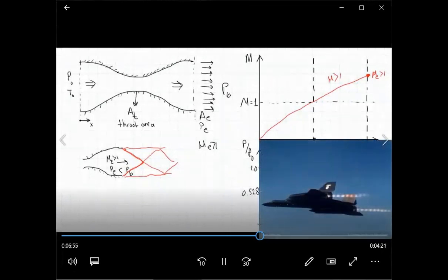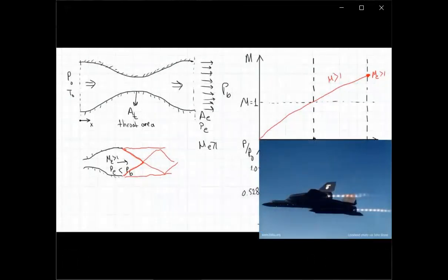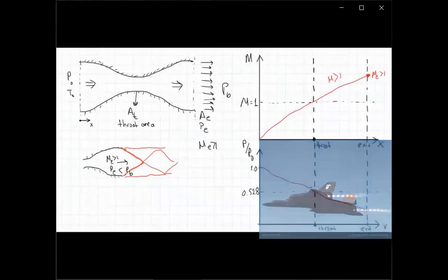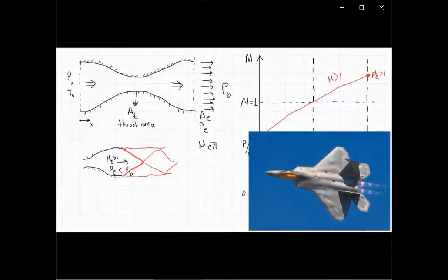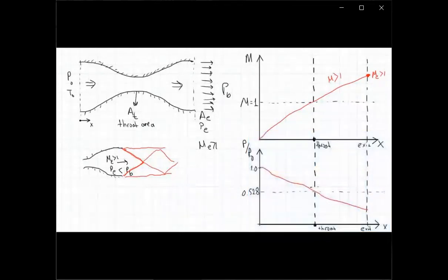In fact, these diamond-like shock wave patterns can be observed at the exits of different nozzles, not only rocket engine nozzles, but also turbojet engine nozzles and turbofan engine nozzles for fighter aircraft. So in this case, let's write it down, is called overexpansion. So this is an overexpanded nozzle, this scenario.